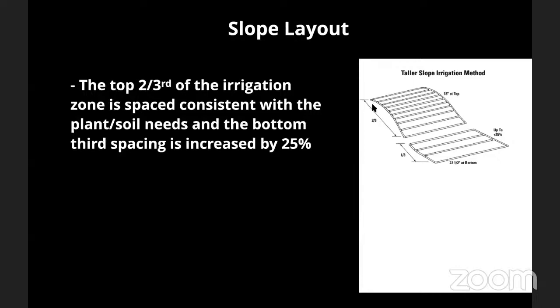And so that might mean that if you total need to run for an hour, that maybe you might need to run for 20 minutes, let the water soak in for an hour, run it for another 20 minutes, let the water soak in for an hour, run it for another 20 minutes. And within your irrigation controller, most irrigation controllers either have a function called cycle and soak, where you can automate that by telling it how long to wait or the maximum runtime for the zone, or they have what's called multiple start times, where instead of saying an hour, you can say 20 minutes and have it start 3 different times.